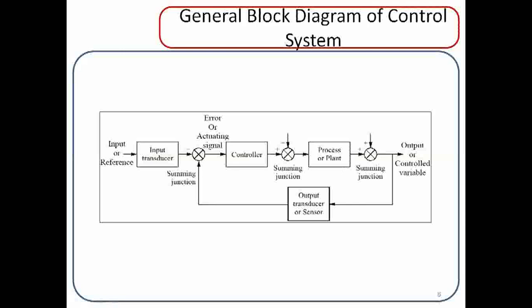Upon completion of that process, the inspection will again be carried out at this unit, and the results will again be fed back to the reference channel. When the obtained results are satisfied with respect to the input or reference channel, that particular object will be okay, and the output is within the control variables. So this is the operational phenomenon of a closed loop control system.